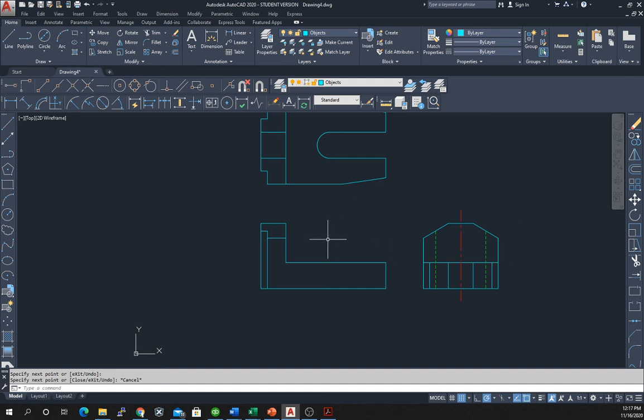Okay, so final things that we need to do to this drawing. We need to add that there's some kind of change in dimension. There's a feature change here that we need to put down here. So we go to our line. We just use our tracking line to bring down a line and make a line there.